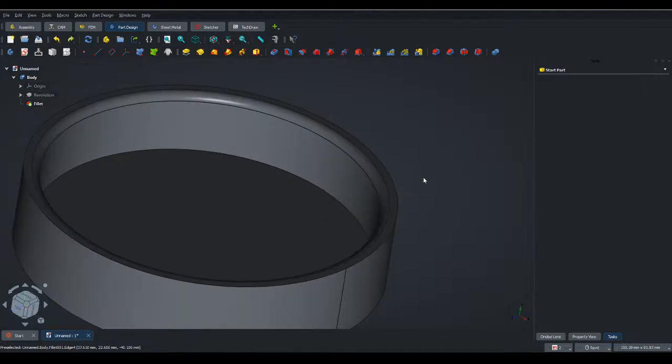In Fusion, the algorithm for the part geometry is smart enough to understand that on a 5mm thick wall, if you put 2.5mm radius fillets on each corner, it automatically combines them into one seamless 5mm radius arc. But it looks like Ondsel is not smart enough to detect that and do that automatically.